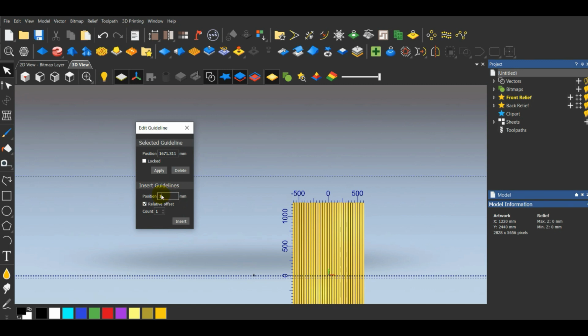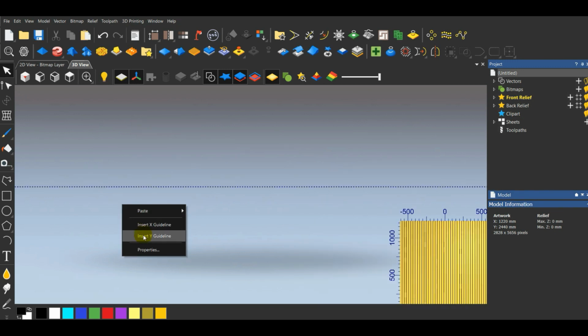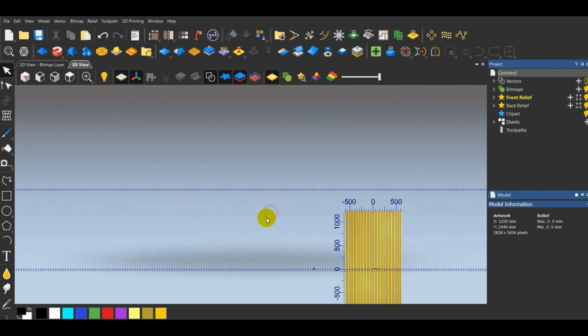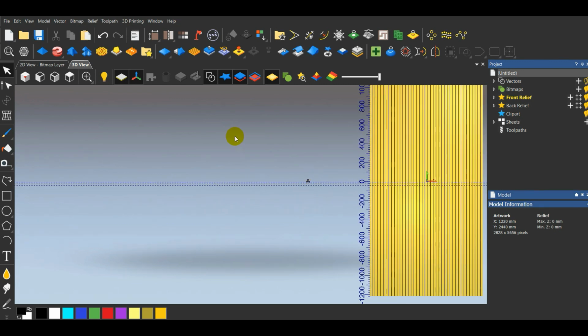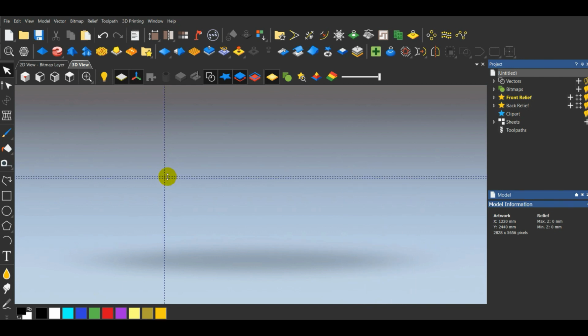That is our cutting depth for the 31.6 cutting width, which I just explained with this tool. Make one horizontal. See, now we are making a Z modulation curve, or you can call it a fluting curve, the tool traverse path.